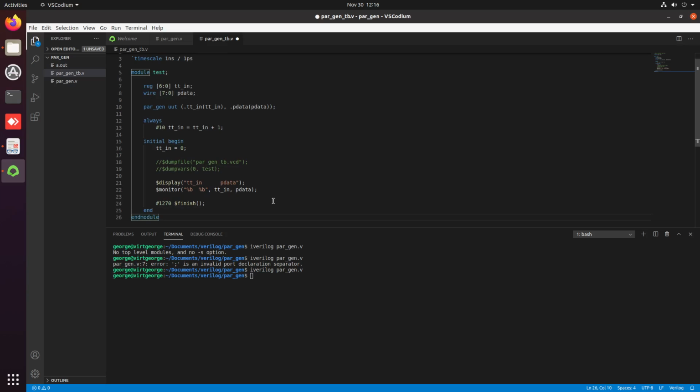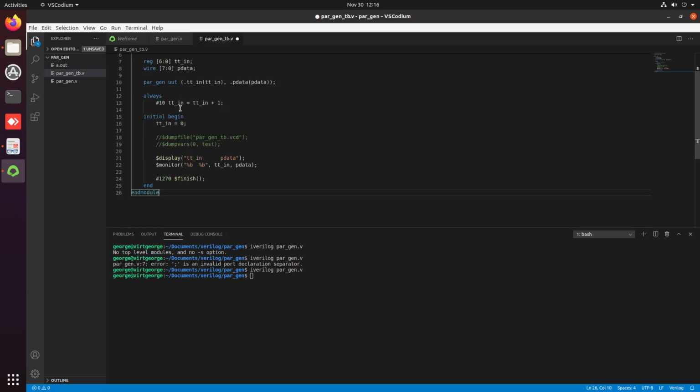In the Verilog course, you may find other test benches, in many examples, that generate random numbers to test a circuit. So sometimes, if you don't really want to test all the possible inputs, you can just use that test bench and generate a few numbers only. Let's save it. Let's now compile with the test bench. Oh, we have no problems here. So let's execute the simulation.